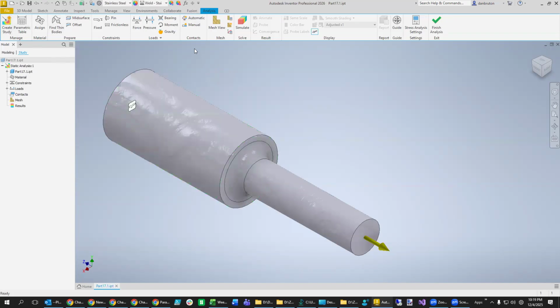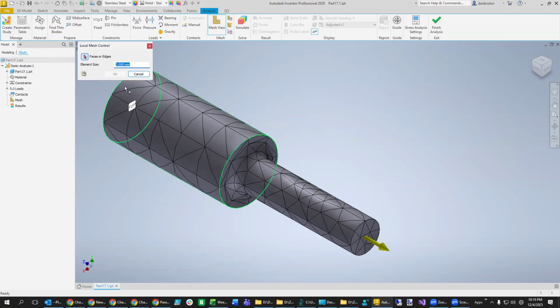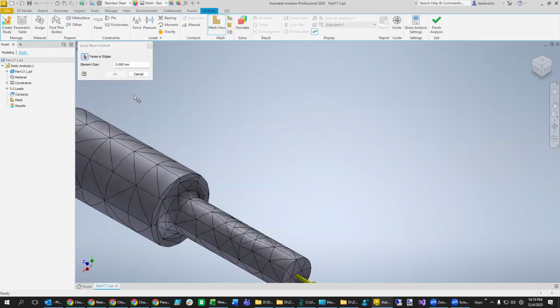So then I think we can just do our mesh view and say that that's clearly not enough. I'm just going to guess at some values here. So in this area, I'm going to put 0.1, just like we did in this other one. And I'm going to put it around this one because it looks like bigger elements than out here.